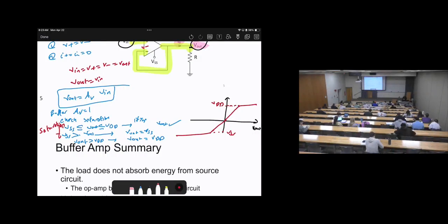For example, let's assume my bound is between 0 to 10 volts. My target is to reach 15. But since my limits say the maximum I can have is 10, I will give the output 10. Then there should be an indication, like a light bulb, called saturated. Then we can understand that there is something wrong, which is that the output is not what it's supposed to be.